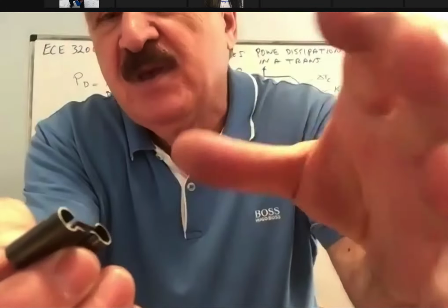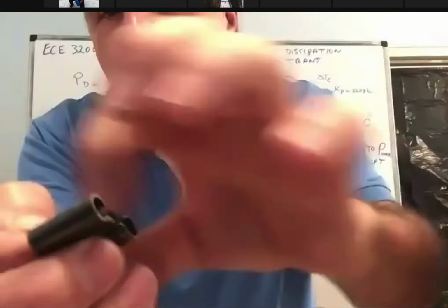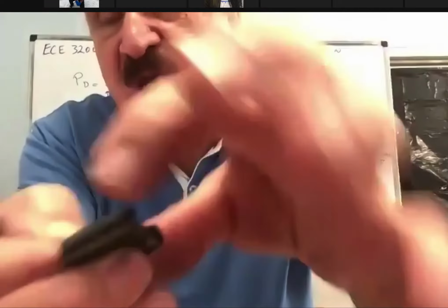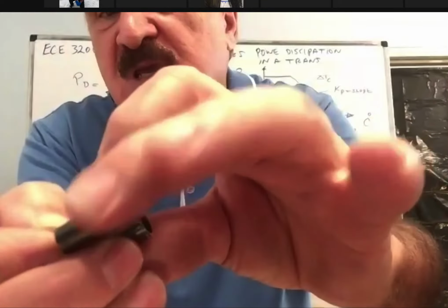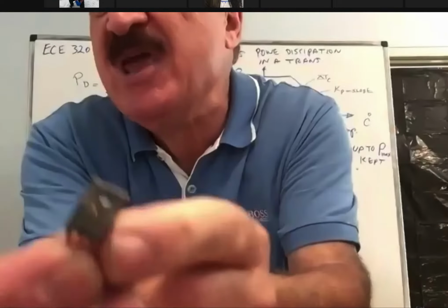So it makes the heat transfer higher from the whole thing, with the stud, with the casing or heat sink, into the air, as opposed to the metal alone by itself, because of the exposed area.